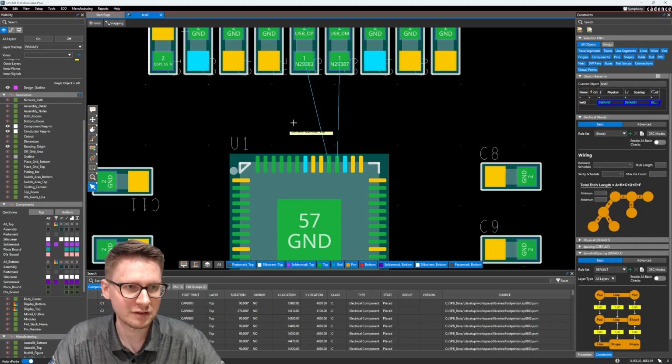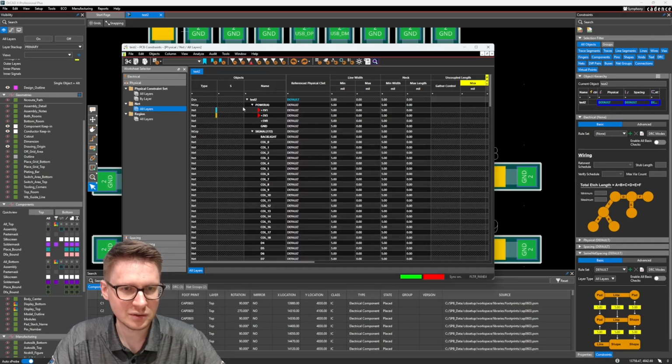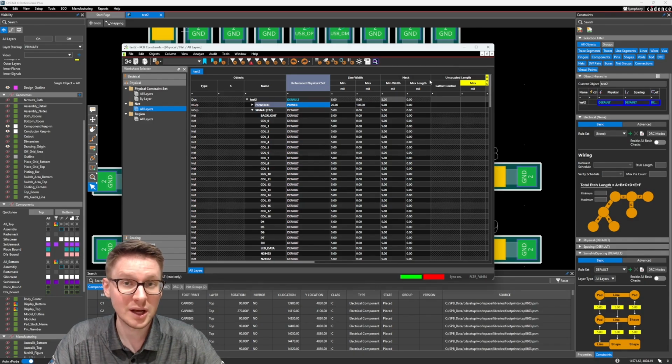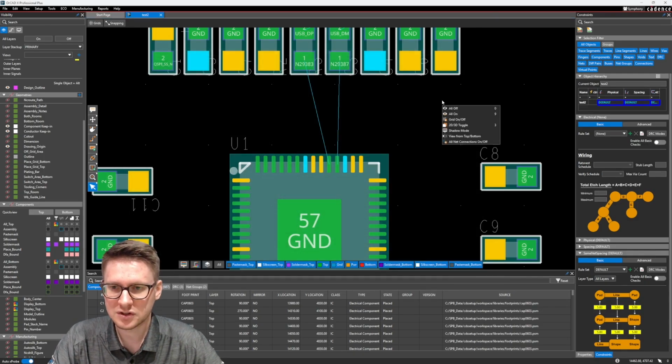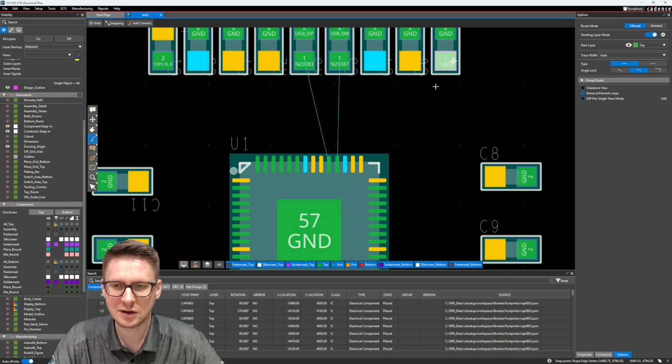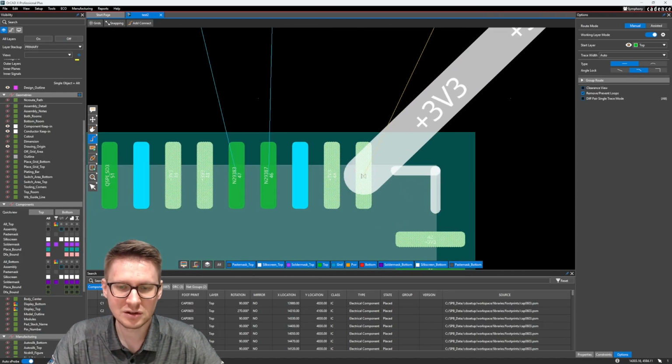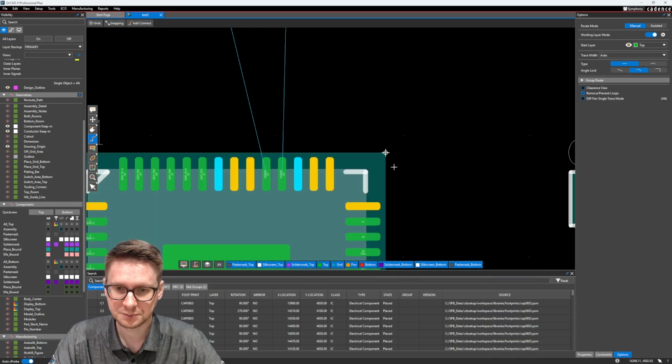Oh, we actually have to assign it to the nets. Let me do that really quick. So nets, to the power net group, I want to assign the power constraint set. So you'll see automatically it assigns that 20 mil width, 20 max width. But if we start to route one of these power nets now, right now we have this really thick trace, and it's not going to be routed very easily to our microcontroller.